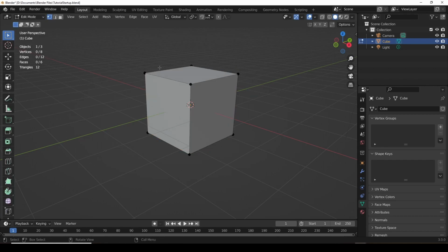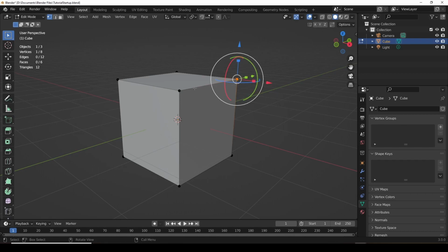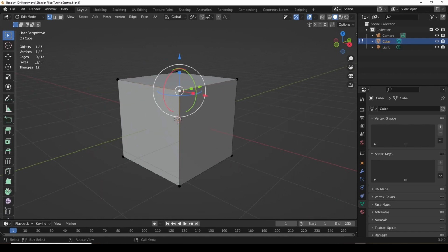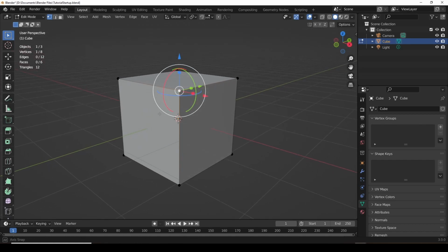As we showed before, we talked before about what comprises an object. You see we've got these vertices and edges and faces. We want to make sure that we don't have duplicates that we don't see, that we're not aware of. So this will help us know exactly what is comprising our object in terms of vertices, edges, and faces, to make sure there's no hidden stuff that might really mess up our modeling and our rendering. So this is going to be very helpful.